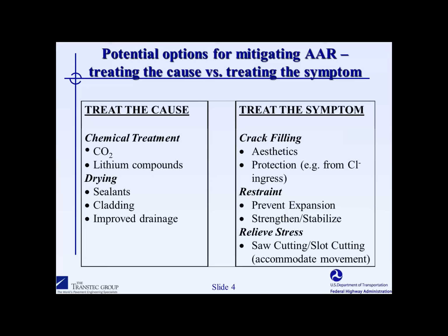We'll spend quite a bit of time talking about drying out concrete through primarily the use of sealers, but I'll also talk about some other potential methods of drying the concrete out. And here the goal is to lower the relative humidity to below a point where ASR will no longer be a driving factor. If we look at the right side of the slide, we have the treatments of the symptoms, and you'll see here that some of those involve just crack filling.